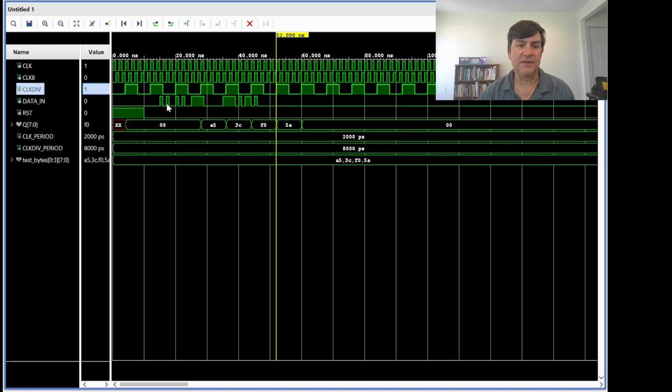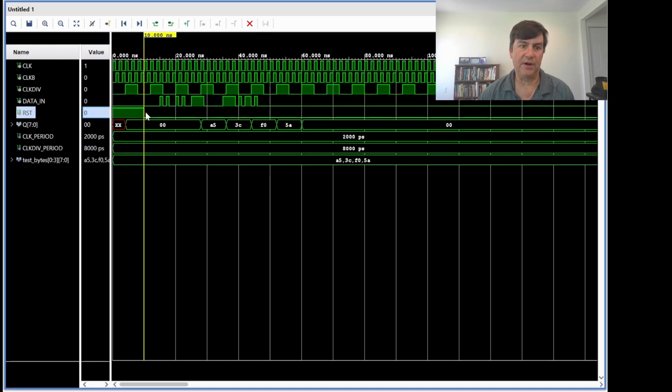Now, the question is the serial data, when exactly does it start reading the serial data? You can actually shift the serial data relative to this reset. It comes out of reset right here. And you can shift this data and you will get bit alignment eventually once you get it in the right position, and that will give you the correct sequence here for your parallel data. But when exactly does it start reading these bits?